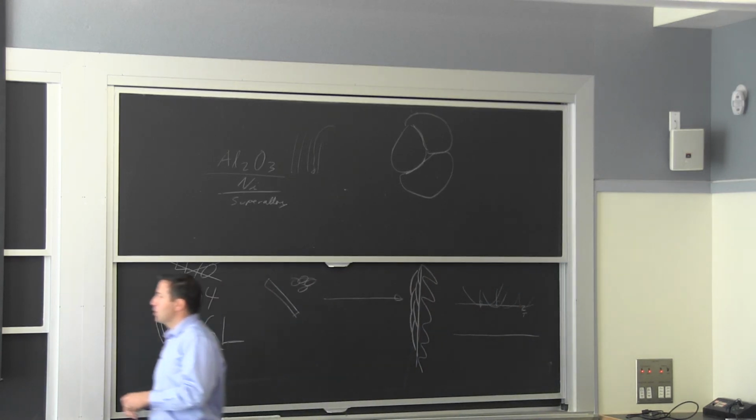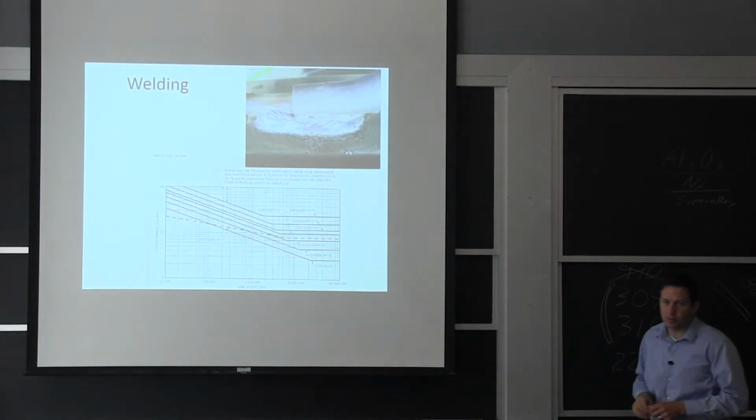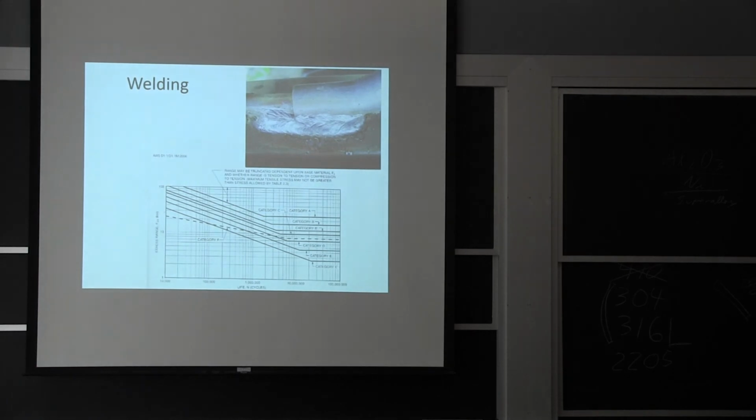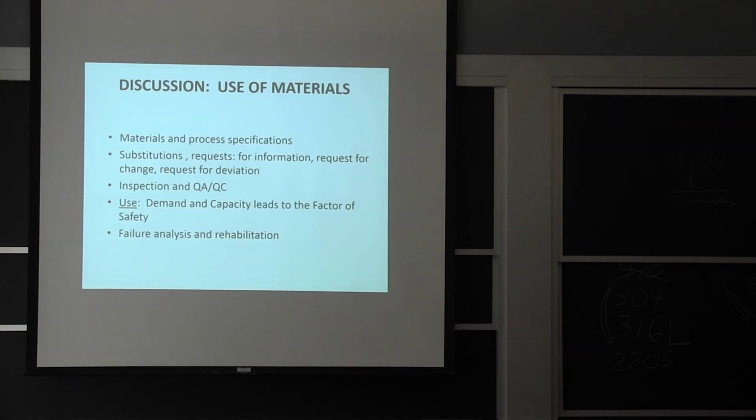The main drawback of welding is the consequences on cyclic loads, because you create a cast structure, you create that heat affected zone, you create all these residual stresses. So if we're talking about putting compression on the surface, well, you're putting tension when you're doing welding. So it's a problem for that. I think you get the idea.